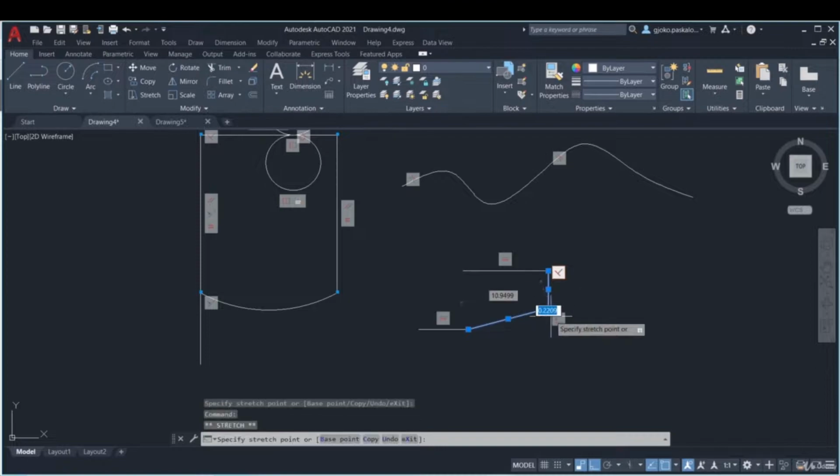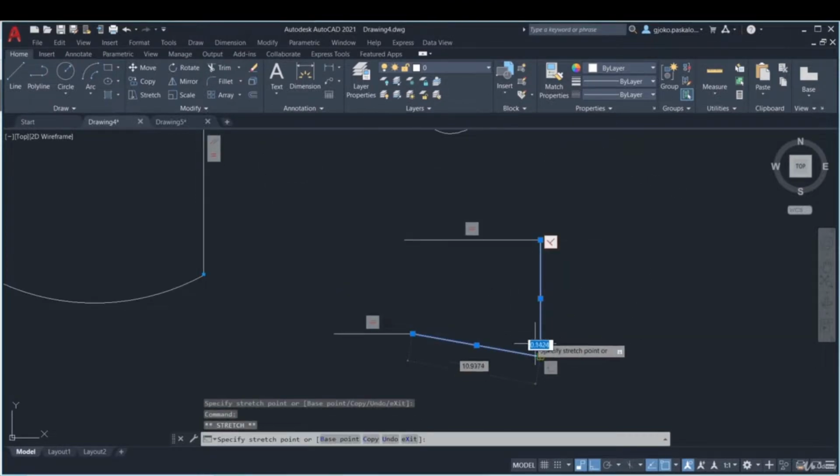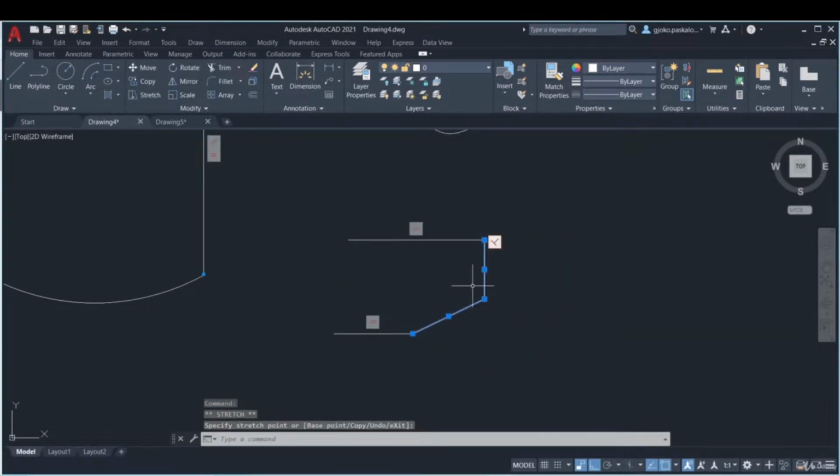So I use the ortho mode, and you can see that horizontal constraints were made on some of the lines. And actually with this option, the constraint will be assigned quite strictly. You can see I have constraints on all the lines, even on the dots between the lines. So the moving capability of the drawing is limited.